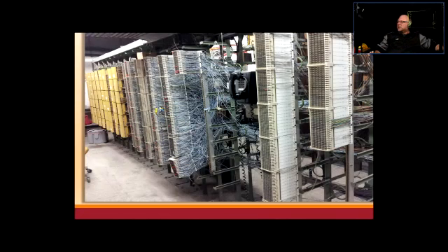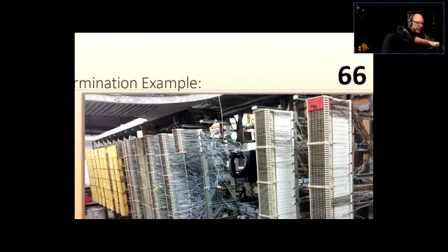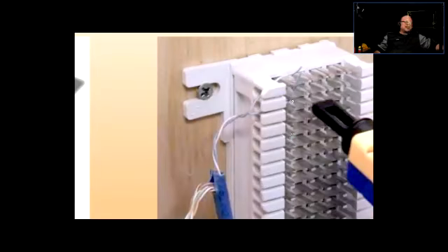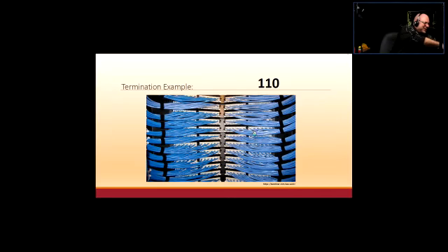All right. So the other wires from the other store would be somewhere on the other side. It looks kind of intimidating because you walk in there and there are so many wires. If you just look at the whole thing, you're going to get dizzy. But now, when I'm telling you all this, it becomes less and less intimidating, because even though there's a whole bunch of wires, you're looking for the one you're looking for, right? You're looking for a pair, and a pair is supposed to be terminated on the 66 block in this way. That huge room was just a lot of these, all right? So I hope it looks less intimidating to you right now.